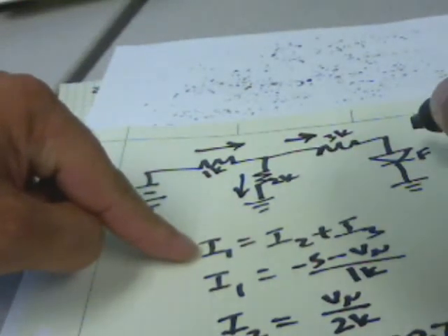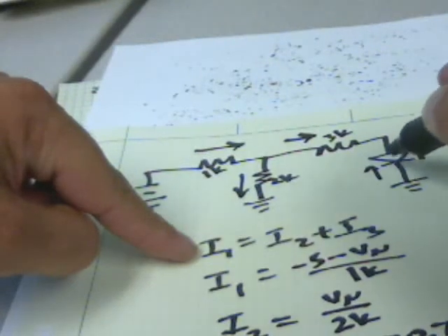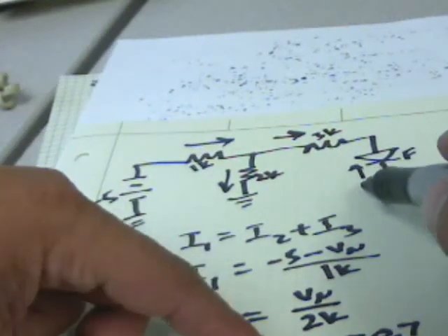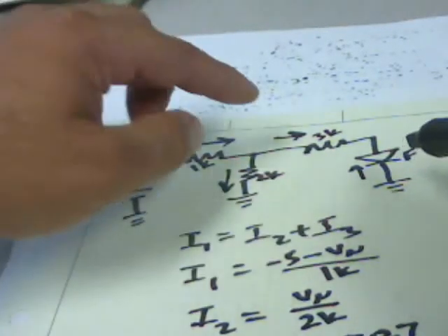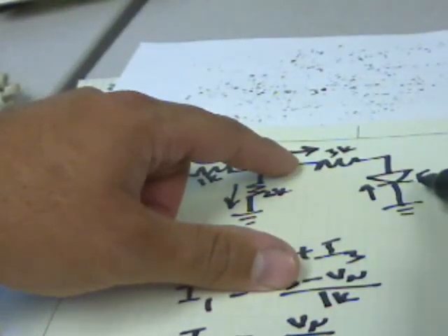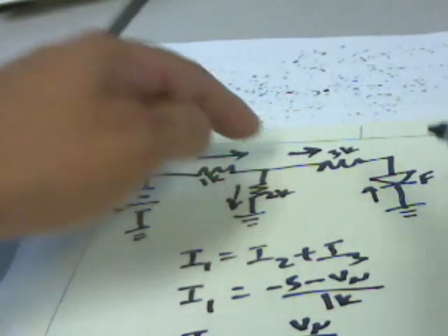Now we look at this and we say, if the current says it's going that direction, then we know it's obviously wrong, and that has to be reverse biased. If we get a negative current over here, then it has to be wrong. We could have made an assumption that the arrow was pointing this direction, but then we've made contradictory assumptions. We've said that this is forward biased, but the current's going the wrong way. So we expect a negative number in that case.